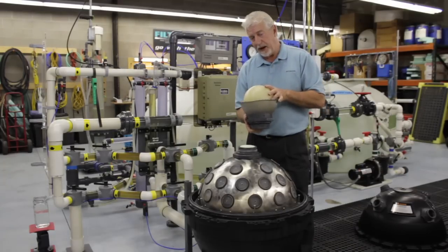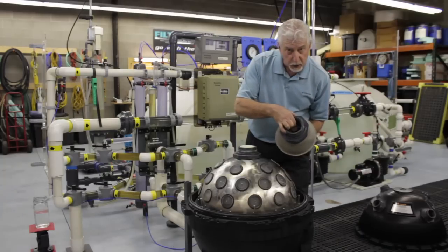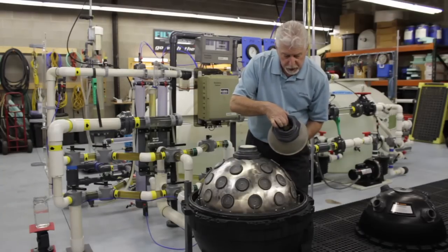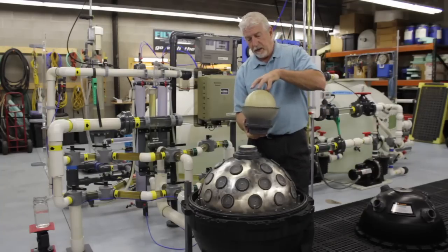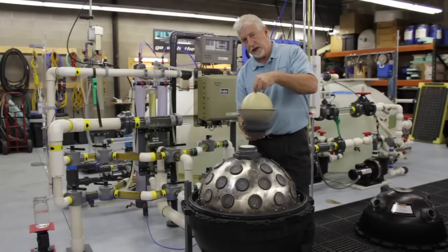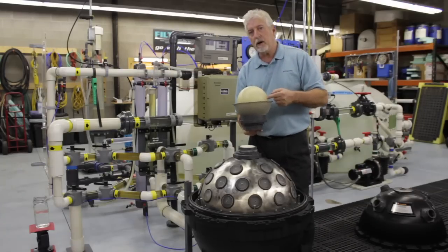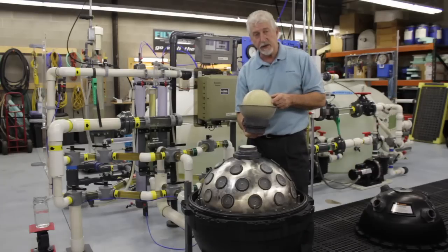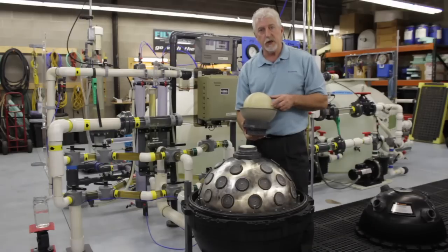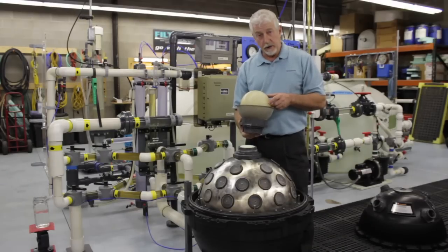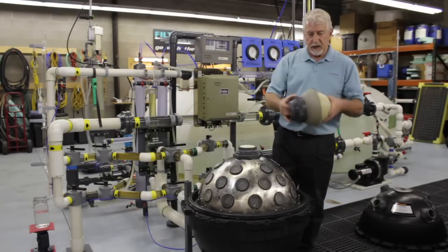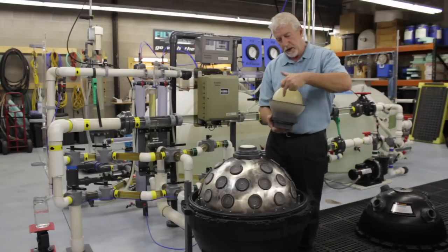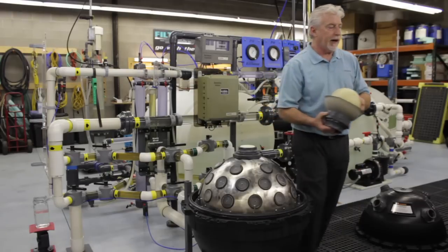When you reverse the flow in the backwash cycle, there's a shuttle valve which has a web, and when the water goes the opposite direction, it pushes the valve up and it closes the flow to this spot here, and the backwash ball will have jets drilled into it in a helix pattern that create the 16 foot per second velocity, high velocity backwash that quickly, in a water stingy fashion, backwashes the media in a very chaotic and turbulent backwash cycle. Then when you go back to normal flow, the valve comes back down, reopens this, filtered water comes in, enters the slot, out the pipe in the bottom.